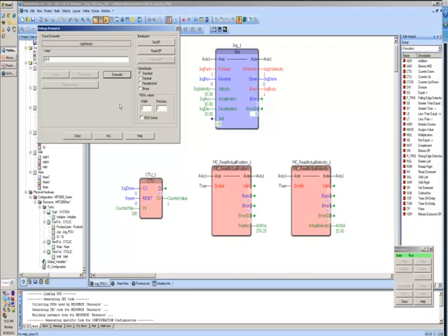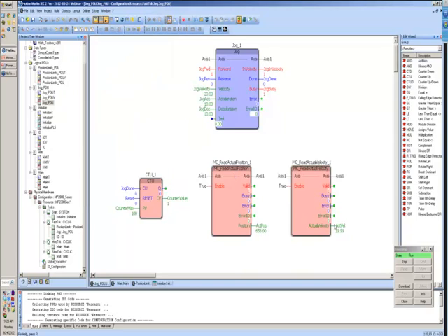Or speed or decel value. Right. And you can see that here in this jog function block as I showed earlier. Right now, our jog velocity is 15. You can see our actual velocity down here is also 15. If I go ahead and change our jog velocity with an overwrite here, you can see our actual velocity goes up to that same amount. If we were to do that using standard PLC open function blocks, then we would have to trigger the execute. It needs another rising edge in order to change that speed.